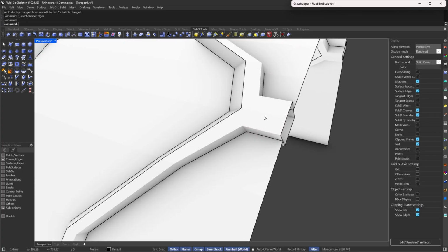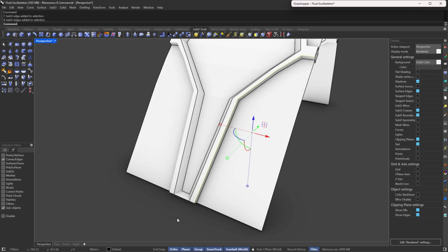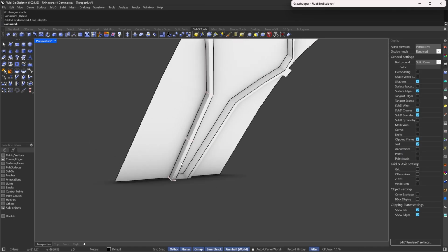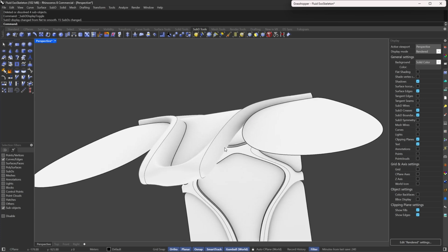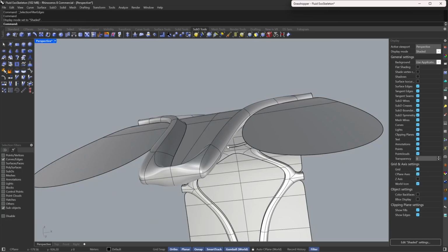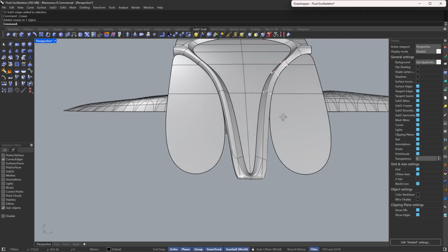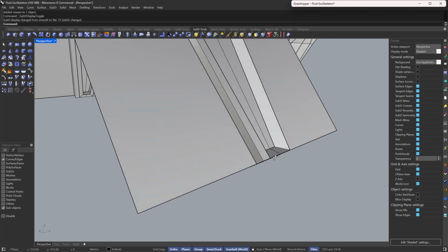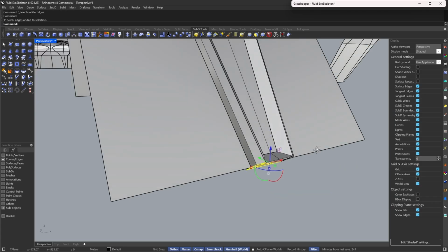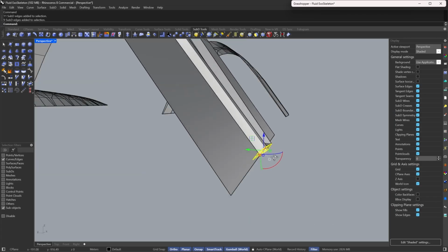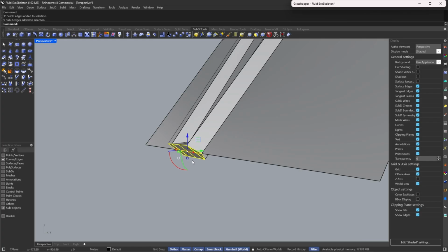And then I'm going to select this and make sure to remove any creases, and double click on this and remove. So you will end up with something like this, but then make sure to select this wire, this one in the middle, select it and make it like this. I think for now this is good, but let's select all of these curves or faces, at least in the bottom, and flatten them.